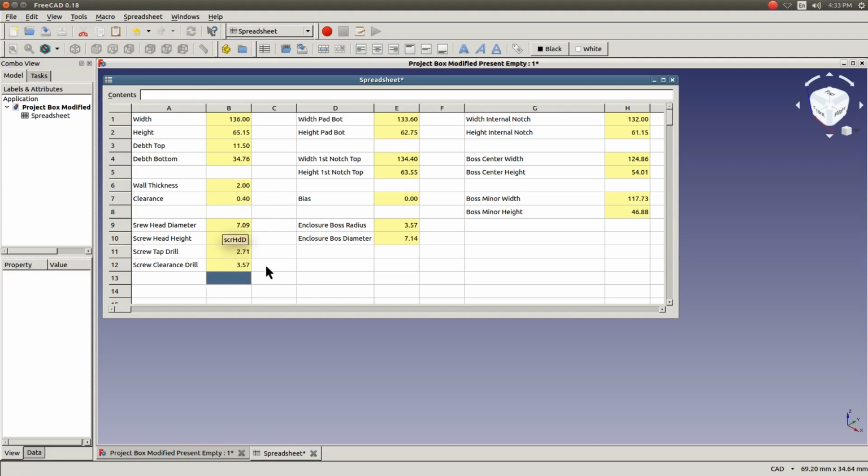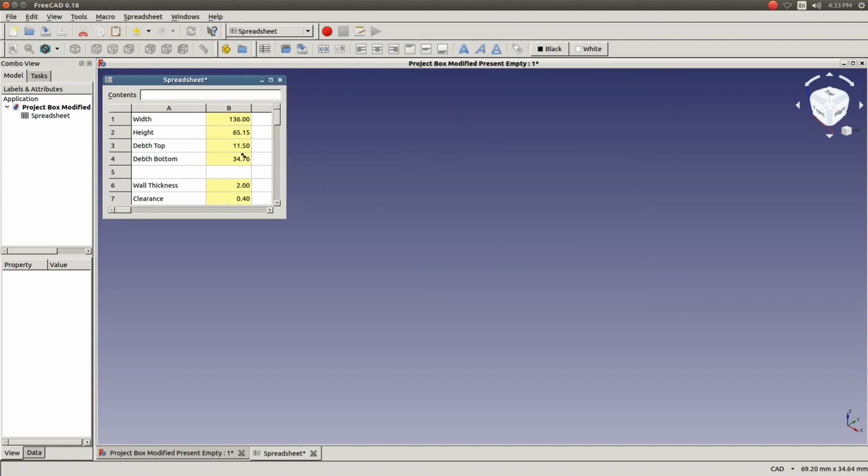Although all dimensions in this sheet are in millimeters, the dimensions for the screw I'm using are for a number 6 screw with 32 threads per inch. You may likely need to change these values to match the screws you'll be using. However, once set, you'll likely be able to just accept these values as default for your project. Let's squeeze this sheet back down so we can get on with creating our enclosure.